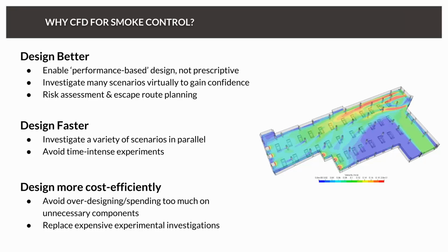And this performance-based design really allows us not only to design this parking garage by following a standard or some recommendations from a fire protection agency, but by really comparing the performance of different designs using metrics you define or using numbers, which is really enabling designers to go completely new paths and massively improve performance and energy efficiency of smoke removal solutions.